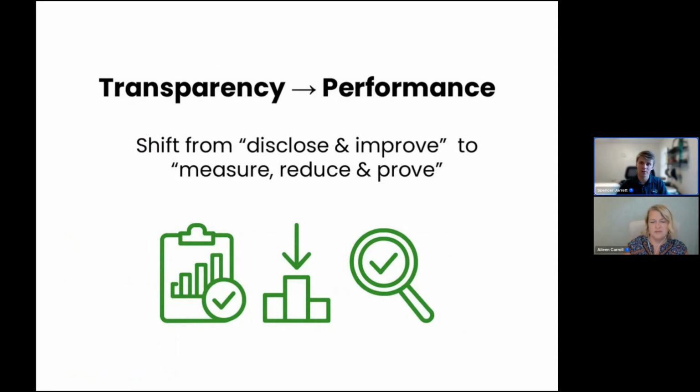Version 5 is a little bit different. Now you need to document quantifiable improvements. So lower GWP values in those EPDs, reduced toxic exposure, and higher recycled content are some of the metrics that you actually need to be looking at for the MR credits. And it's less of just having the information to get you those points.